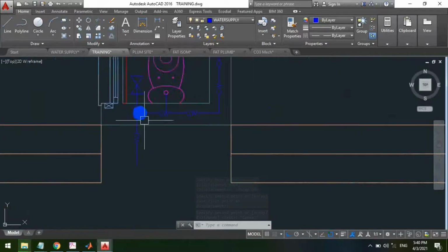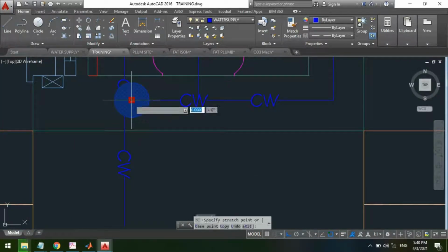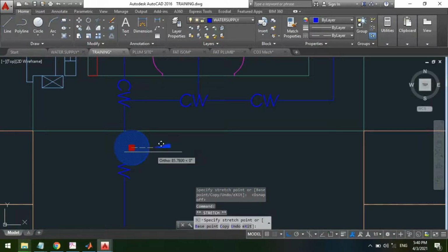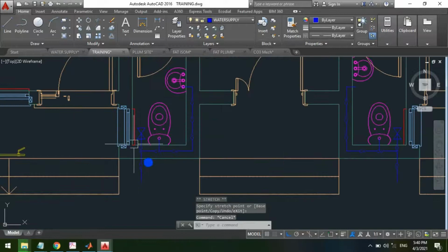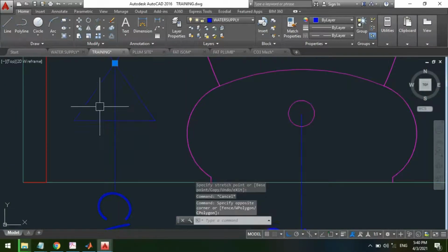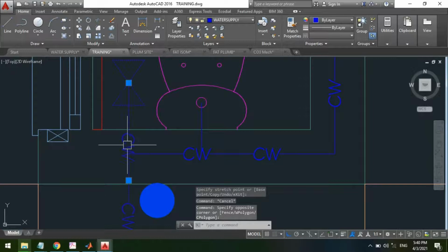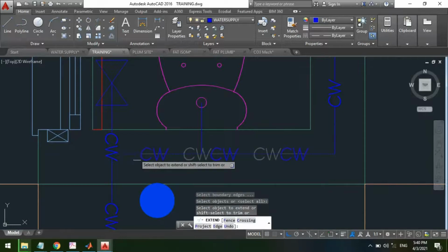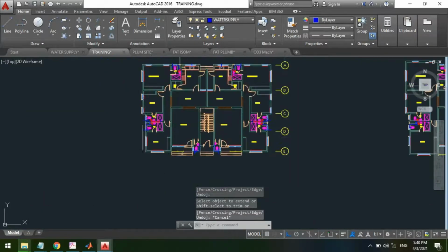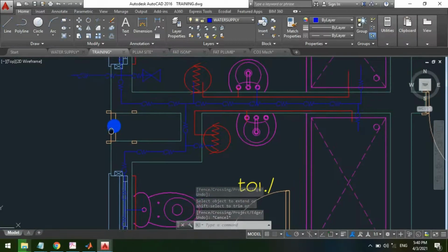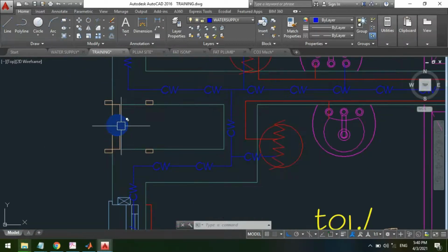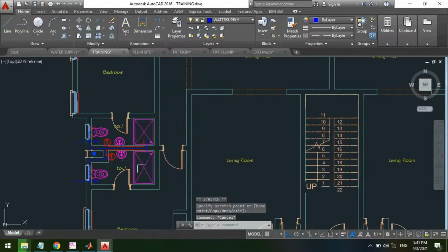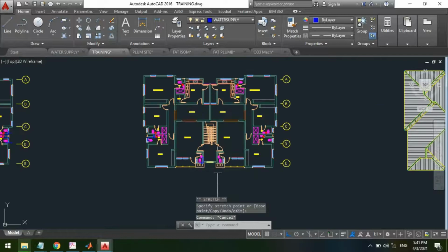With this, I'll be able to determine where the risers will be attached from the ground floor, which implies my riser will be coming from this axis, F3 off. With this, I'll be able to adjust my main for the ground floor so that the pipes won't be touching each other. M enter, EX extend, enter, close. Likewise for this other part, this one eventually entered the duct. So we have our riser here. Let's take it inside.